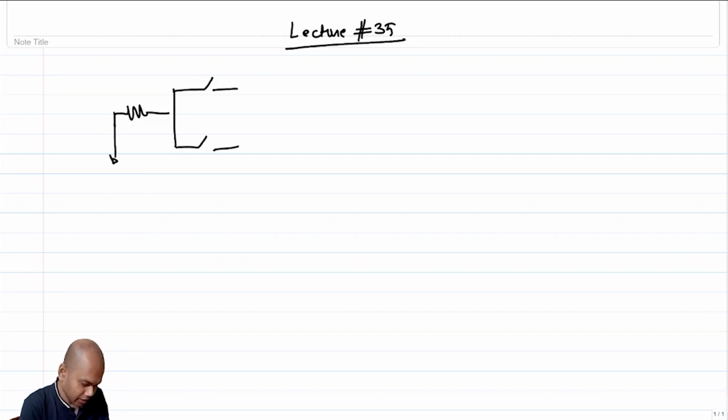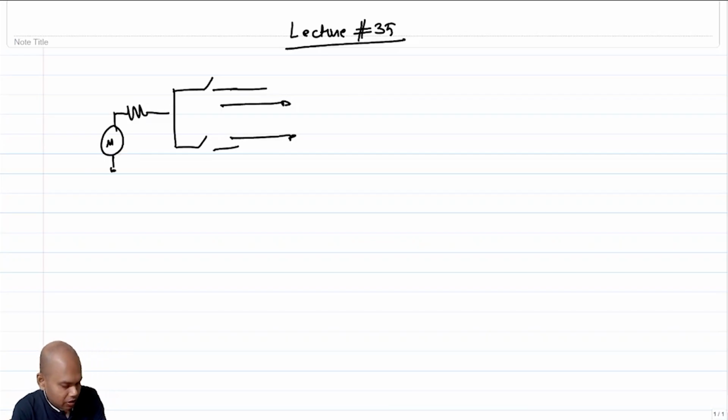I basically said that you have some architecture like this, and it goes into some low impedance node, and the noise from this resistor also mixes, and you have noise folding, and thereby you get an increase in noise floor, right?